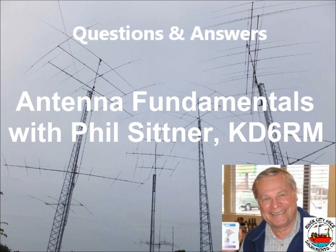Did you also know that there are types of antennas that are non-resonant? An antenna does not have to be resonant to work. It'll radiate something. They all radiate, some of them quite well. Have you ever heard of a Beverage antenna or a rhombic antenna? They perform incredibly well. So there's a lot of different kinds of antennas.